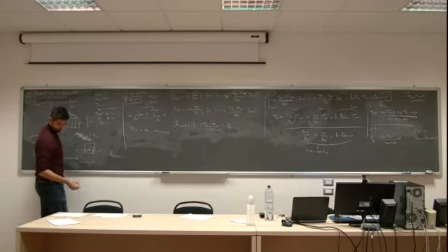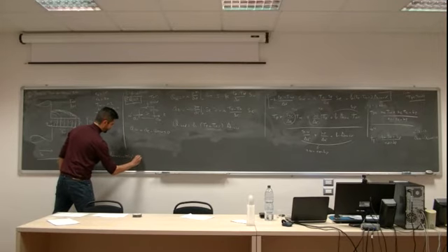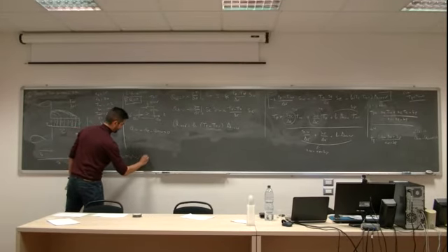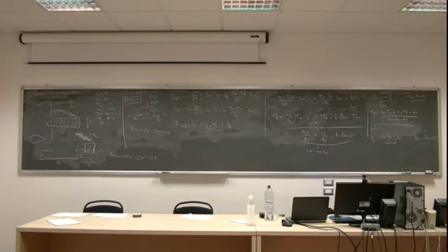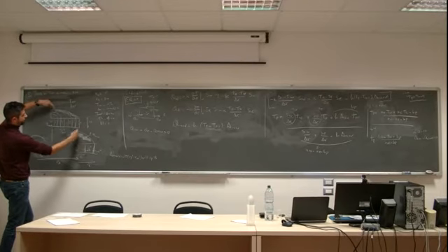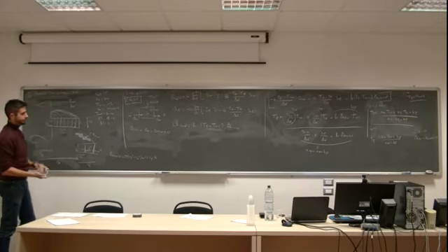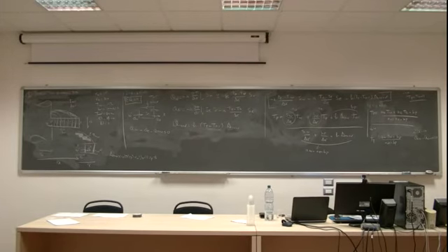For node 7, it's 2 pi RP square RW square plus 2 pi RP multiplied by thickness. I think I'm correct. Yes. Right? The area of convection will be that one, the one below, and the one surrounding. Okay? So we have these equations.